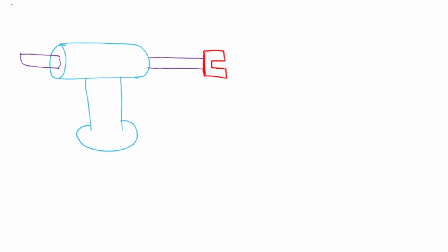This is also 3 degrees of freedom, 3 DOF, but it has 2 revolute joints and 1 prismatic joint. What are the revolute joints and the prismatic joint? Let's try to understand this carefully. The first axis is this one. It can rotate about that axis. So this is my first axis.